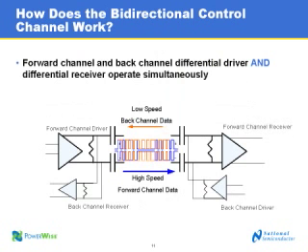So the key thing to know here, and we've said it again and again, is that this is continuously transmitting data in both directions over a single pair. That means that the forward channel driver and receiver are active at the same time that the back channel driver and receiver are active. And this is a National patent-pending technology that was developed in-house.